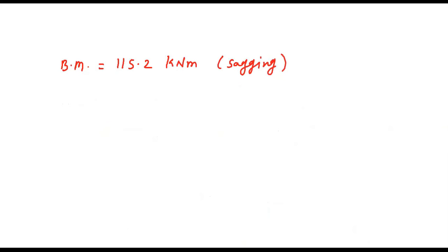And at the last, where are we going to calculate the moment? At the interior support. At interior supports we want the value of bending moment. The coefficients are minus 1 by 12 and minus 1 by 9.